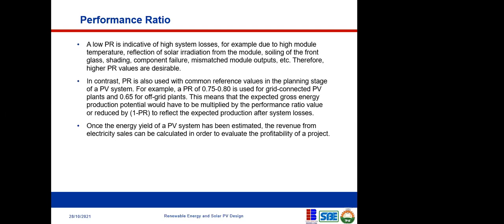When you're doing your battery calculation, you also have to consider your depth of discharge. Otherwise, you mess your design up. So we'll come to that. And this is the problem with some of these people who are going into solar systems without the full knowledge. Sorry, can I just chip in too?